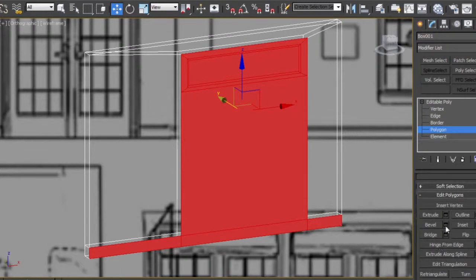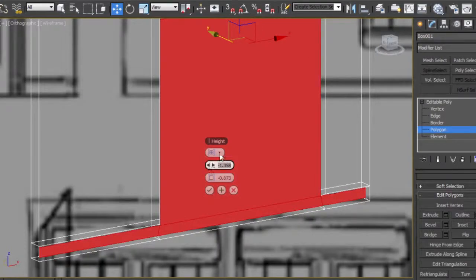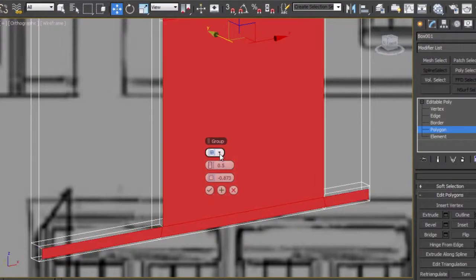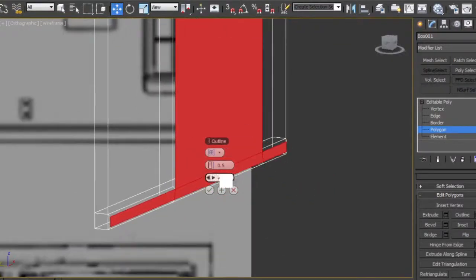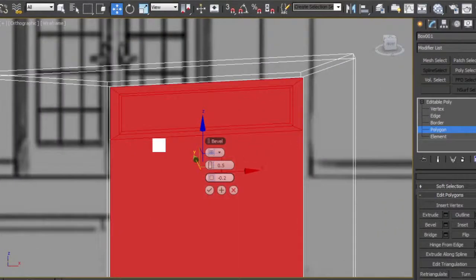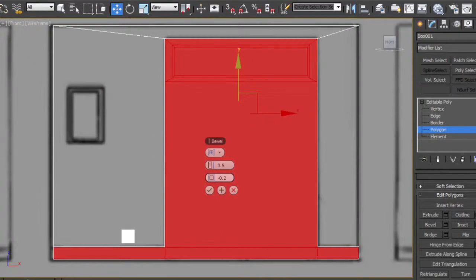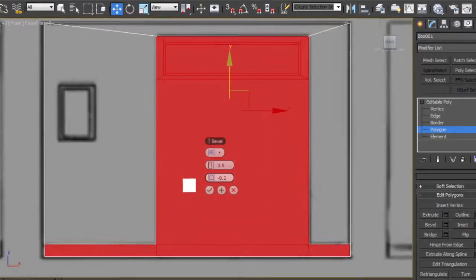So I will hit bevel for an angled extrude, and I want it to come out maybe just 0.5. This is the distance of the baseboard, and I want an angle very, very small, maybe even only 0.2. That would be 0.2, negative 0.2. The slightest bit of angle so that we don't have a terrible 90-degree angle. 90 degrees creates invisible extrusions. This way we have a very, very slight extrude using bevel and a slight beveling of negative 0.2.